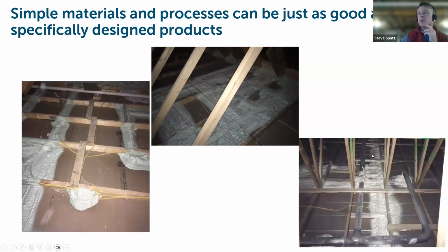The idea of spray foaming all of those stitches this all together so you have a monolithic layer of drywall with no leakage pathways, no penetrations through it. And then on top of this, you blow in as much insulation as you want and or need to meet code and to meet the project objectives. So the key here is that it doesn't have to be complicated. It doesn't have to be specific as far as material options or choice goes. It just needs to be thorough. It needs to be continuous, and it needs to be durable.